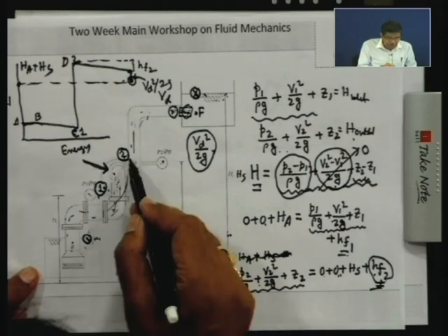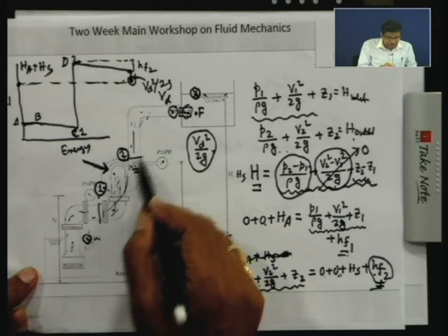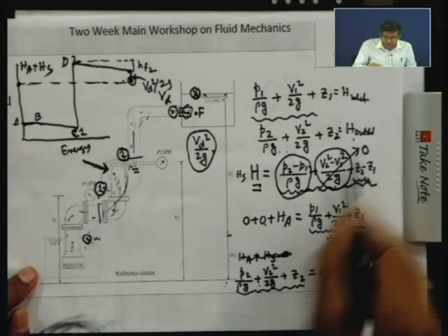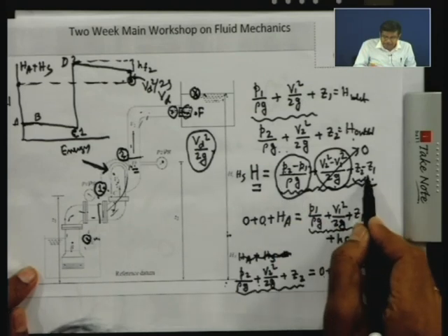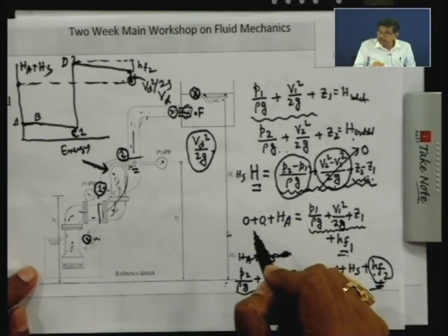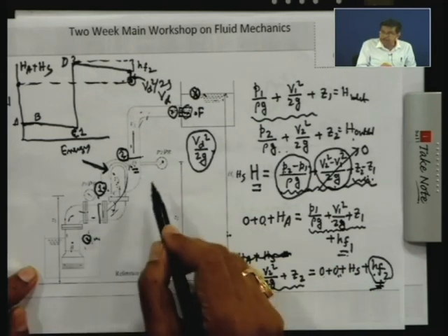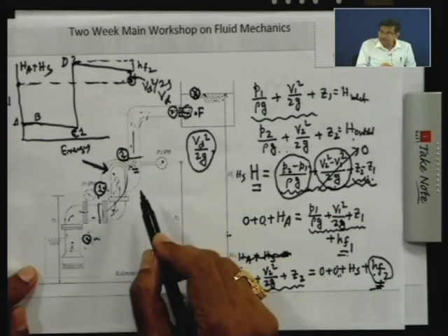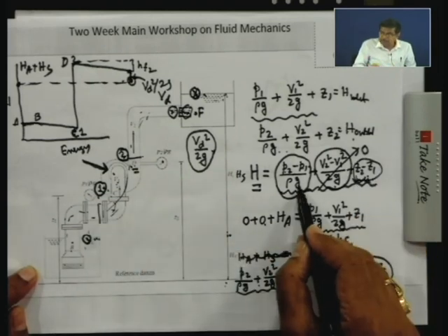By the continuity equation, if the pipe diameters are the same, the velocities are the same. Then the difference between static pressure and elevation head is the piezometric pressure drop, which can be registered by a manometer. If we neglect the elevation, it will simply be the static pressure drop.